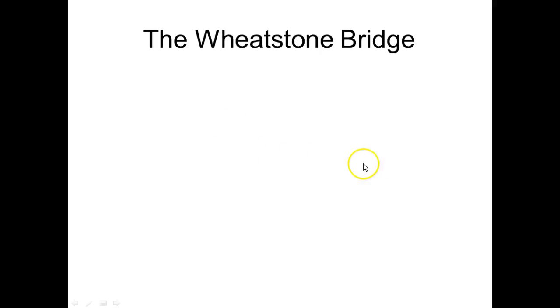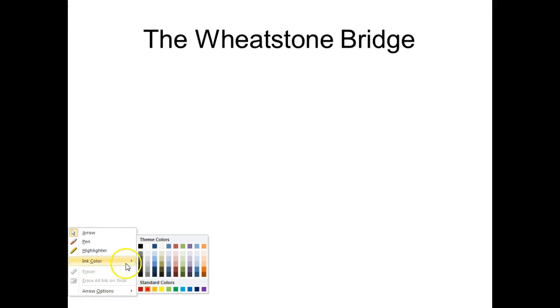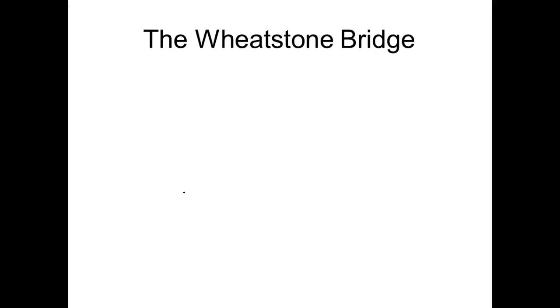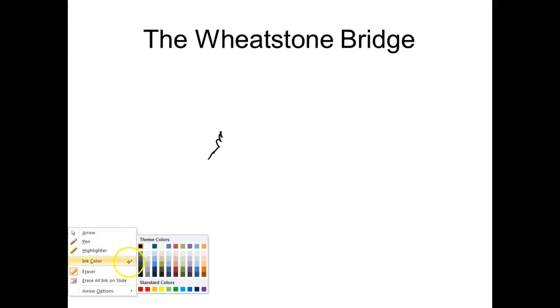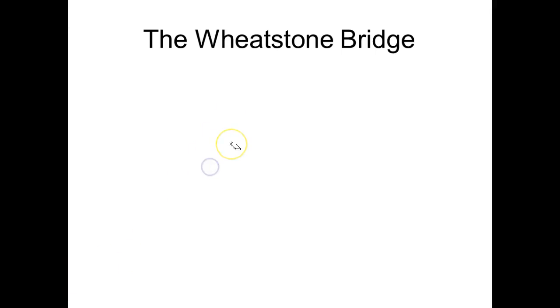But first of all, did y'all talk about the Wheatstone Bridge? Did we talk about the Wheatstone Bridge in this class? I think we did. Yeah. Wait a second. Let me start all over. What we're trying to do is establish a zero reference. So I've got a thermistor, and the thermistor varies its resistance with temperature, right? But what I would like to do is establish what zero temperature is.